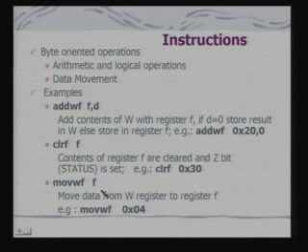Here you are moving data from W register to register F. Now, interestingly, when you have to select the bank, that bank select operation you have to do prior to execution of this instruction. That means you first select the bank, and once you select the bank, then only you execute these instructions so that the correct location is accessed.